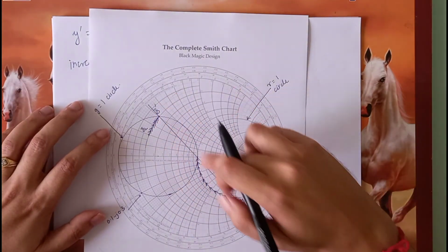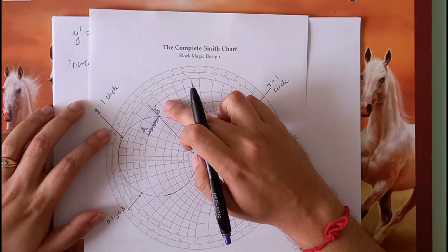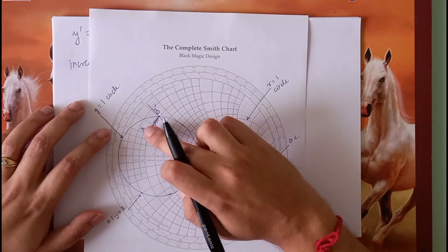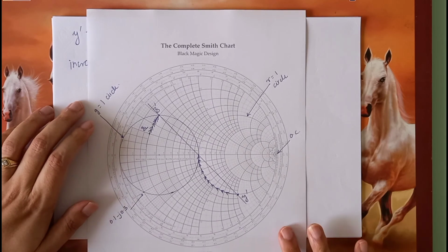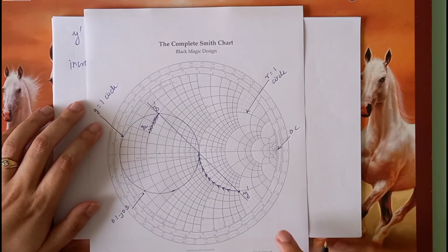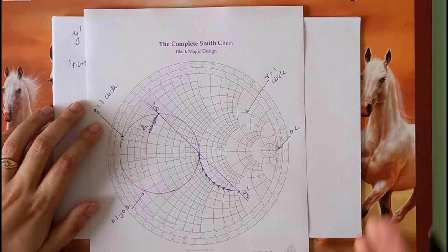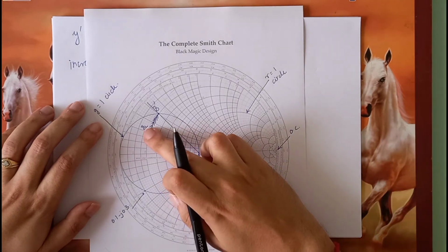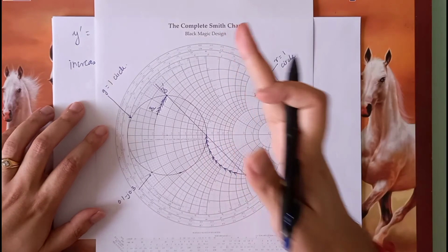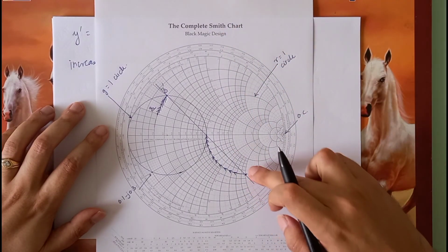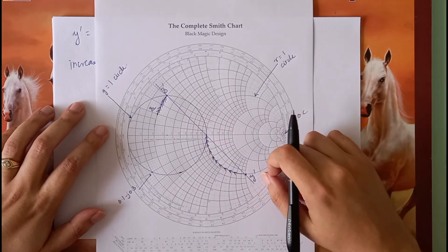If you are on an R circle, going up means increasing of reactance, so therefore series inductor. If you are there on the R circle and you are going down, means you are decreasing the reactance, so therefore it would mean a series capacitor. But now we are on the admittance circles, we are on the conductance circles. So therefore conductance, admittance means increase decrease happens in parallel. In the impedance coordinates, increase decrease happens with series components, but in admittance coordinates, increase decrease happens in parallel configurations.